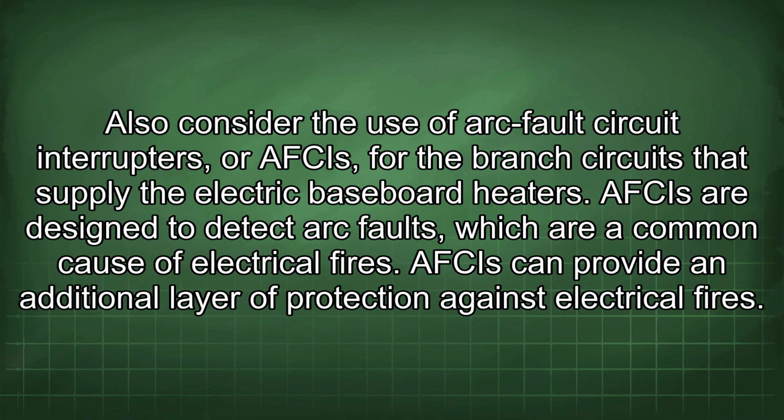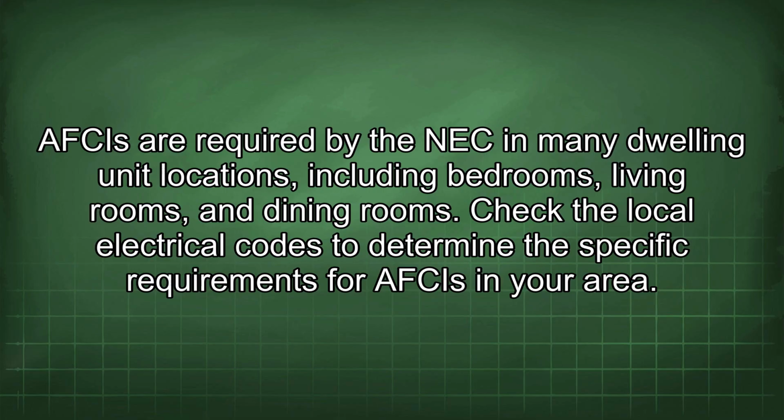Also consider the use of arc fault circuit interrupters, or AFCIs, for the branch circuits that supply the electric baseboard heaters. AFCIs are designed to detect arc faults, which are a common cause of electrical fires. AFCIs can provide an additional layer of protection against electrical fires. AFCIs are required by the NEC in many dwelling unit locations, including bedrooms, living rooms, and dining rooms. Check the local electrical codes to determine the specific requirements for AFCIs in your area.